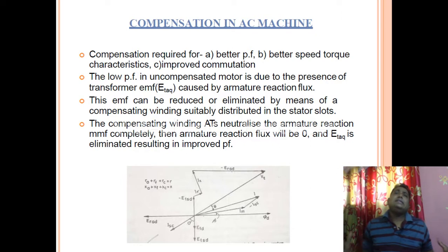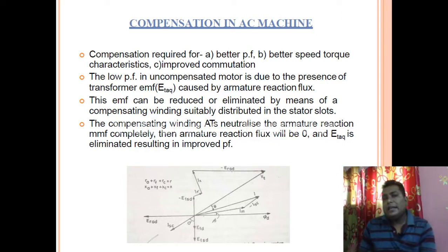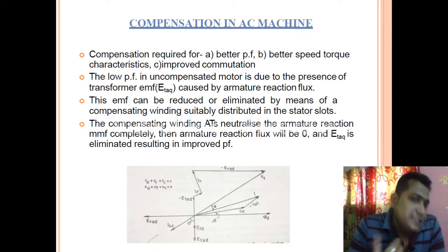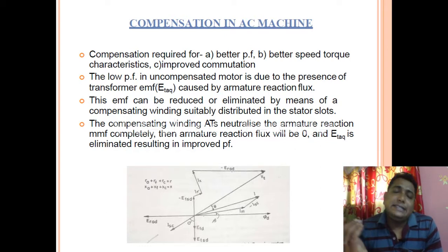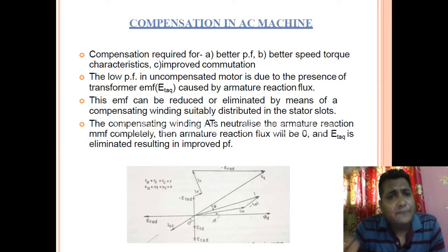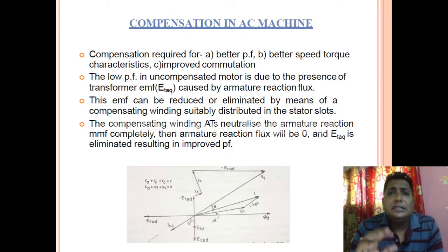So now in case of motors, we know that we have to give electrical supply as input and we will take mechanical energy as output. So when we are giving electrical energy as input to the stator winding, that is the field winding, it is generating some flux. So that flux is cut by the armature winding, and when the armature winding cuts the flux, it is generating some EMF.